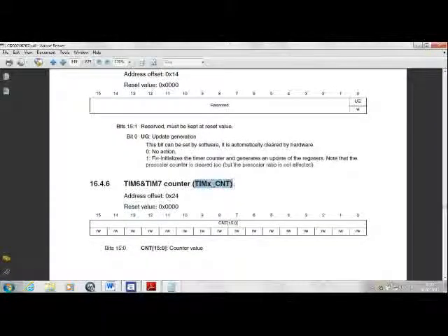This is the actual counter. It is a read-write register. It means that this counter can be dynamically written into and also dynamically read out, so that in a particular application, if you want to curtail or enhance, that is elongate, the timing that was pre-programmed, you can always read and write into this register.